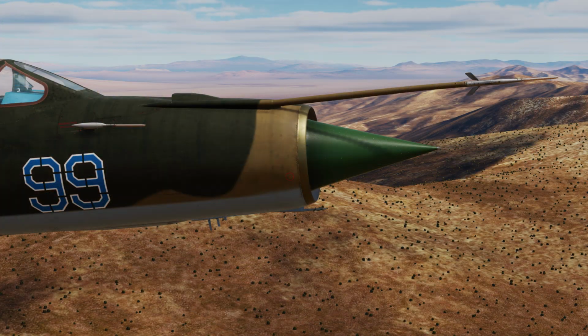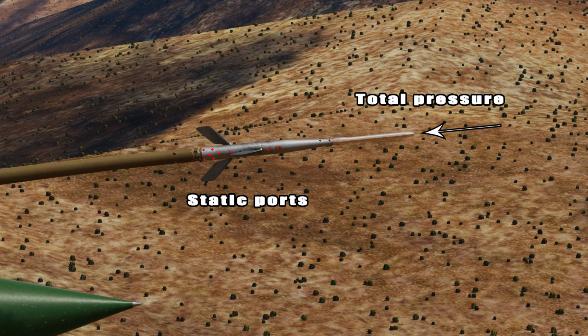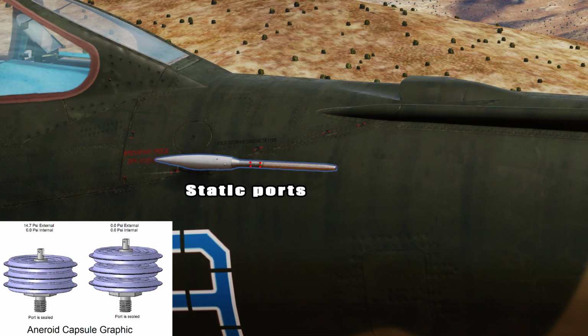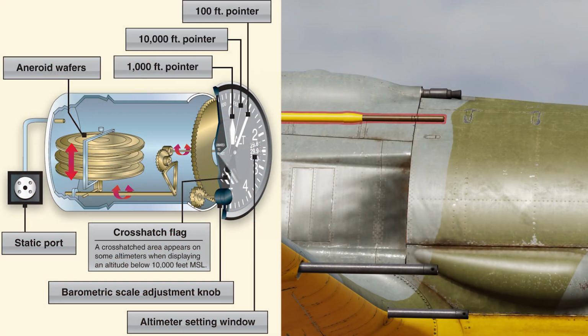This is a Pitot Tube. It features a long tube placed parallel to the aircraft's longitudinal axis, connected to a spring-loaded aneroid capsule, and one or a few holes placed at 90 degrees to it, connected by small tubes to the outside of the aneroid capsule, itself placed inside another sealed chamber.